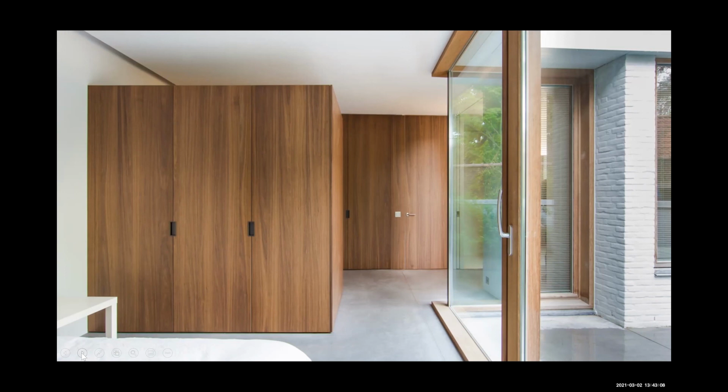The other thing is that a laminate wood grain will not patina, nor will it oxidize, and it will remain consistent in coloration, unlike stained wood, which means if a door needs to be added or replaced in a long corridor, it's going to be far less noticeable than what would happen if it was a wood door.